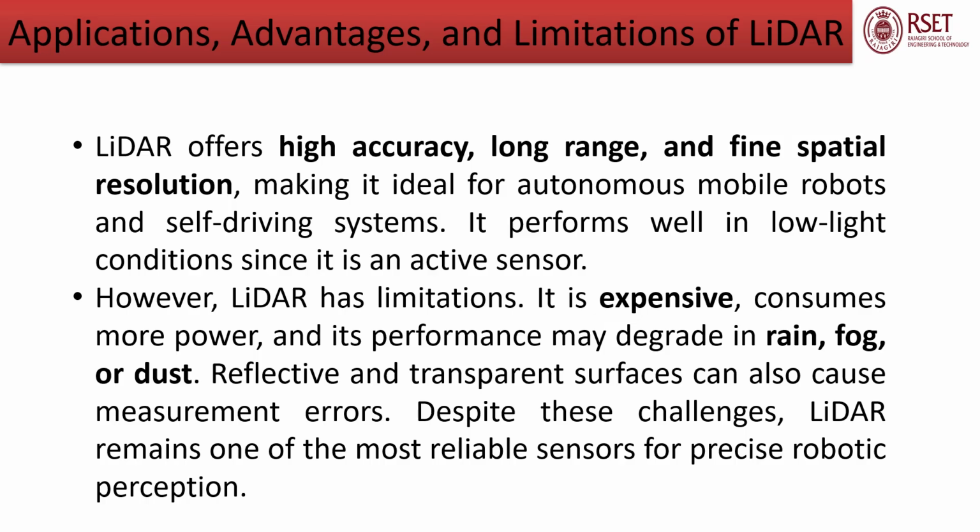However, LiDAR has limitations: it is expensive, consumes more power, and its performance may degrade in rain, fog, or dust. Reflective and transparent surfaces can also cause measurement errors. Despite these challenges, LiDAR remains one of the most reliable sensors for precise robotic perception.